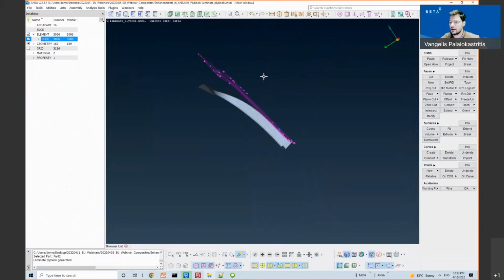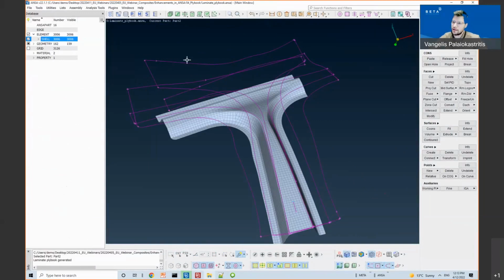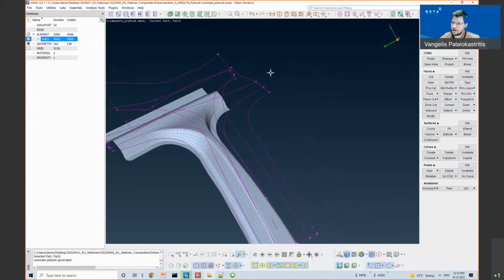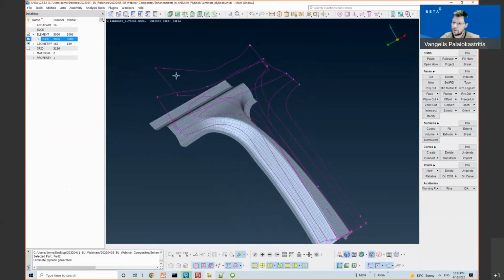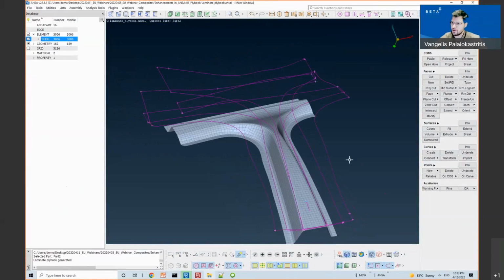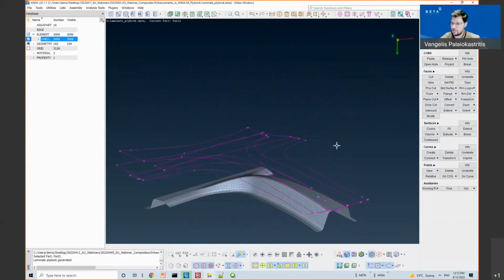Additionally, free geometry curves are created for every flat pattern. So I have the regions, the region of the flat pattern as a curve, and I can export it in an IGS format.